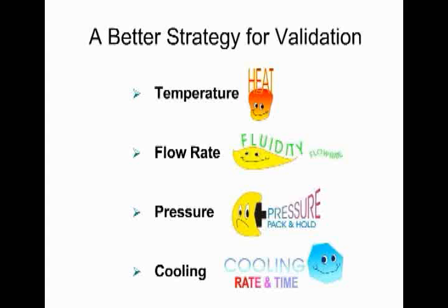Okay, so for those of you who have already seen the 4 plastics variables, it's the foundation of scientific molding, understanding the part you're making from the plastics point of view: plastic temperature, plastic flow, plastic pressure, and plastic cooling. When you change the perspective on process development to focusing on these areas, shifting away from machine-dependent variables to plastic-dependent variables, you have a much more efficient and effective process.